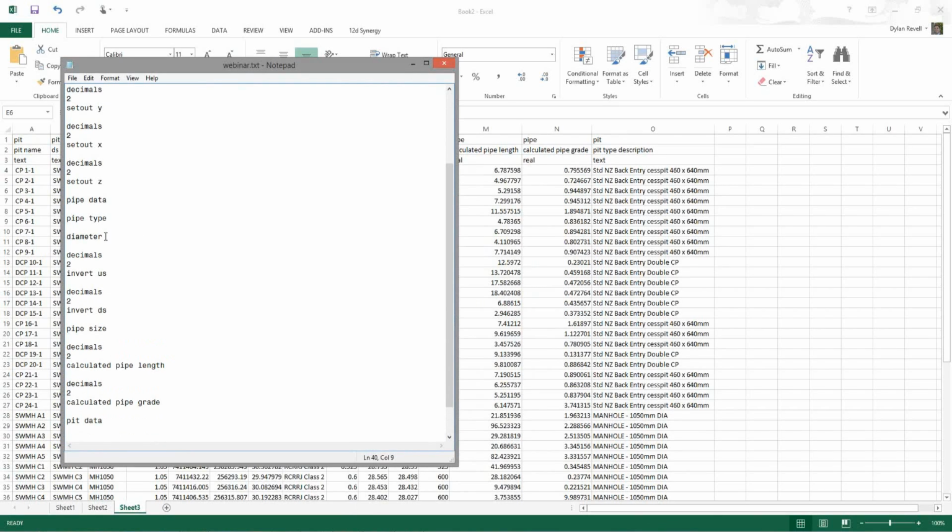And with the diameter attribute, as currently the unit is in meters, what we can do is apply a scaling factor to whatever that value is in the attribute by activating the command factor. So I'm going to factor by 1000 whatever value is in the diameter attribute.